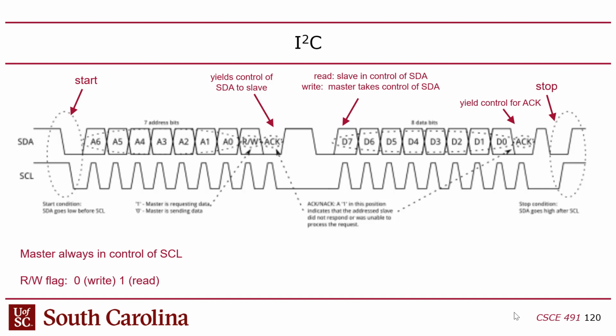So now keep in mind that this is the open drain bus, meaning that if no one's driving, if no one's touching the bus, it's going to be high. And when I say bus, I mean both of these wires will always be high when no one's touching them. In order to bring it down to 0, that takes an active pull down from somebody on the bus, right? So the idea is that if there's no transaction happening and the bus is idle, it's going to be 1 and 1. They're both going to be active high because no one's pulling down, everyone's just chill. And these guys are high because of that pull-up resistor. That pull-up resistor, which is a passive device, is going to make those wires look like they're active high, logic 1, right? So that's the idle state of the bus.